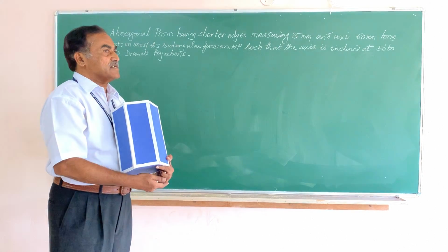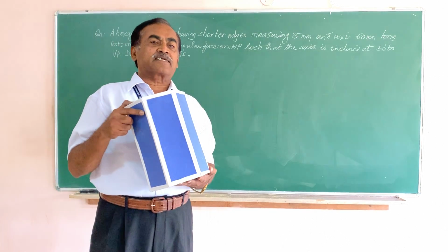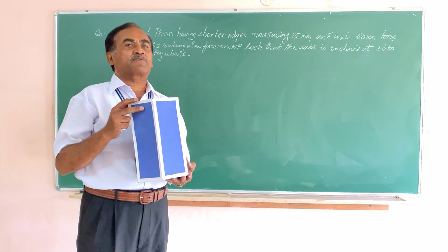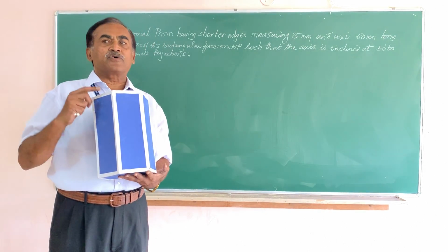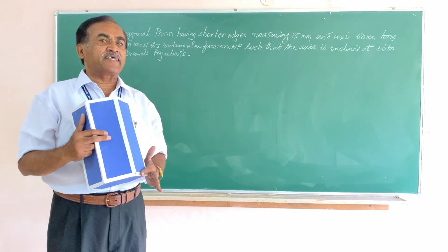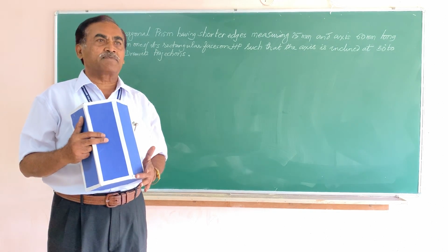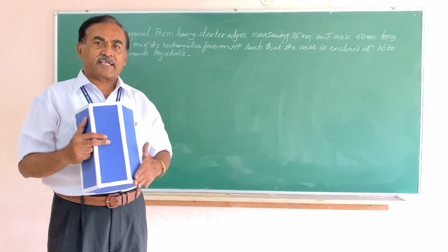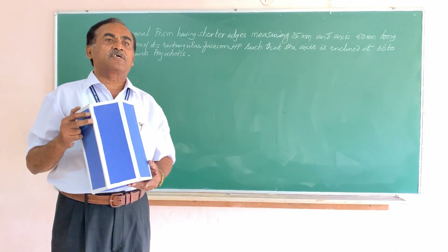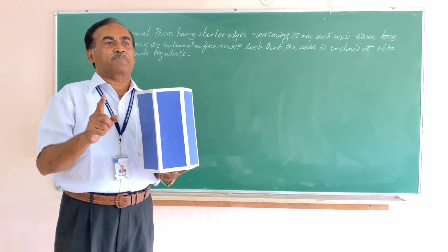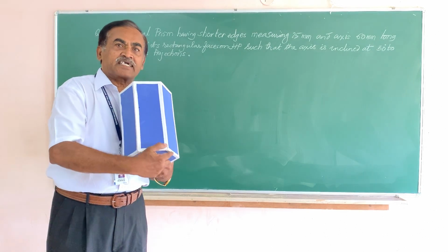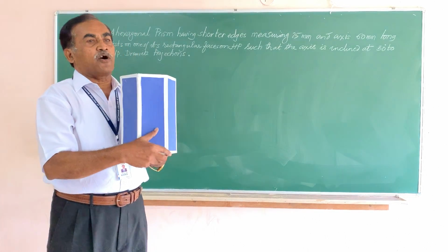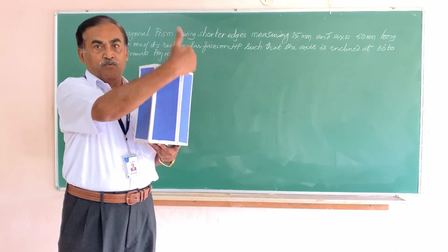Now, before that, let me tell you about the placement of the object. So, initial placing of the object plays a very important role in the projection of solids. Now, I told you in the previous sessions that whenever any of these pyramids or prisms has to rest on the rectangular faces in case of prisms, triangular faces in case of pyramids, we have to place the object initially on HP such that one of the shorter edges of the bottom face will come to the right side of the observer, and that will be very obviously perpendicular to VP, the board here.